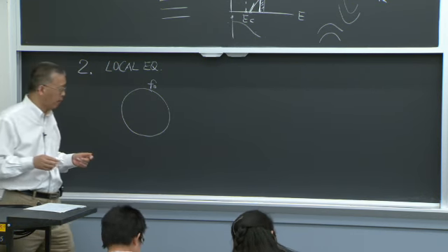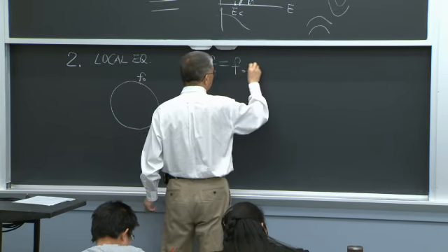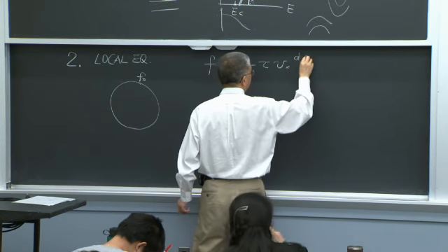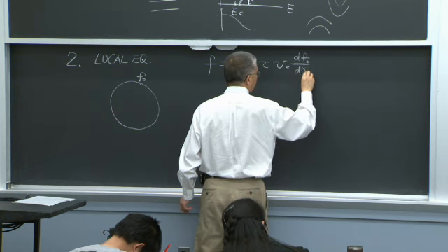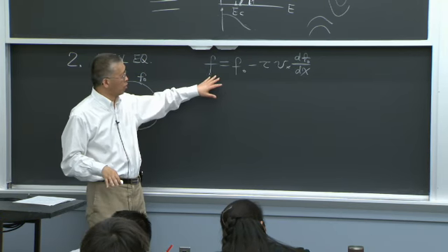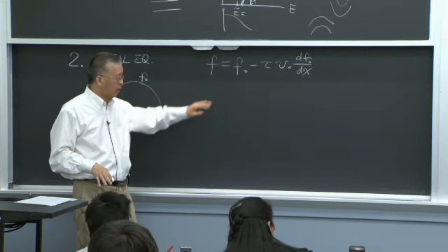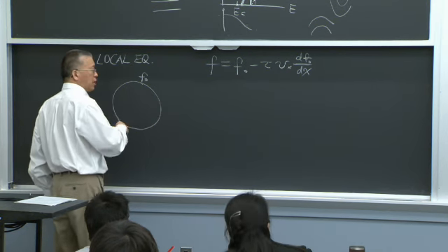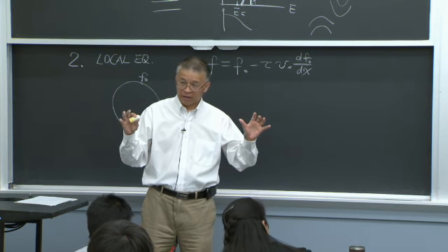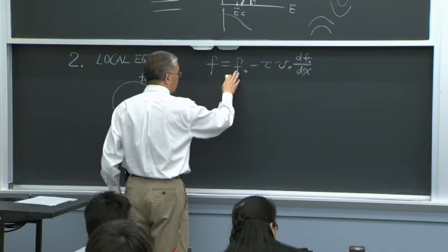So you don't have net flux. That's an equilibrium. And if you look at the simplest form of a solution, it is f = f0 - tau vx df0/dx. This is the simplest form we used to derive the Fourier law, for example. What really gives the flux is the deviation.